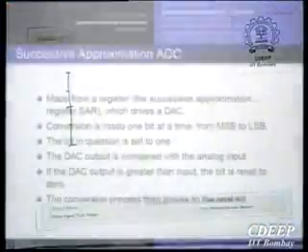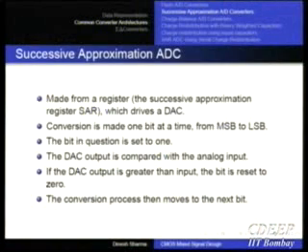Right? The idea is to say that I will take of the order of n clock cycles. So that will take many comparisons. These comparisons will be done at different times but by the same hardware. Okay? So this is the common strand which will run in the rest of the converters. So that is what I am trying to do. So essentially the idea is this, that I will not have fixed references.